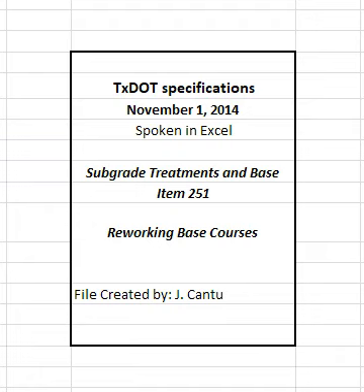4. Construction. Perform work to the width and depth shown on the typical sections for the type of work shown on the plans. Construct and shape exposed subgrade to conform to typical sections as shown on the plans or as directed. Proof roll in accordance with Item 216, proof rolling, when shown on the plans. Correct soft spots as directed.